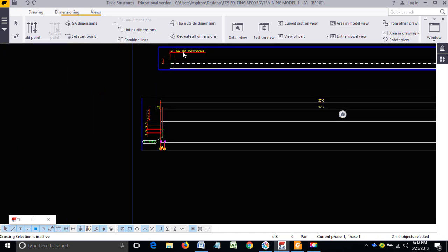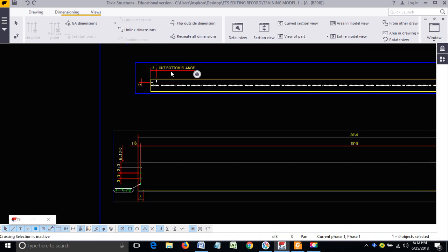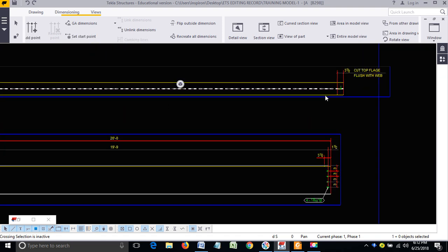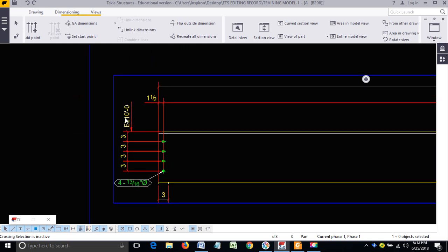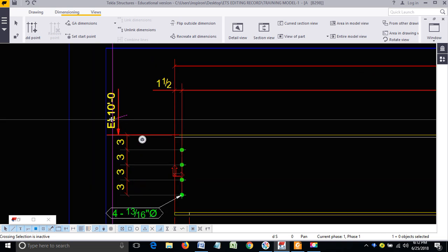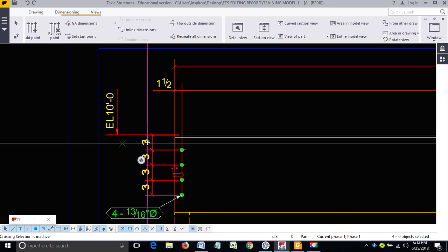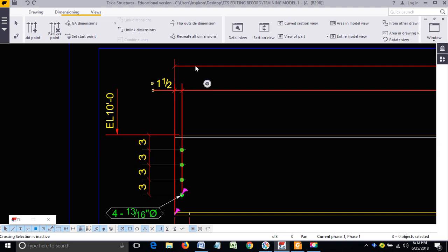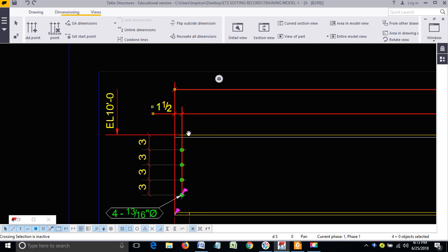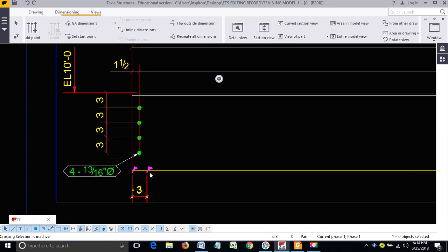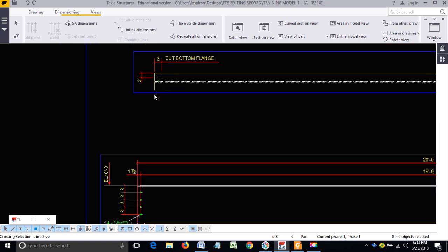Only the top view is very clearly visible, so we have to provide the cutting in the top view. The elevation mark should also be somewhat outside, and this dimension should be kept near, and all the dimensions are also not aligned properly. So these are the errors our people commonly make.